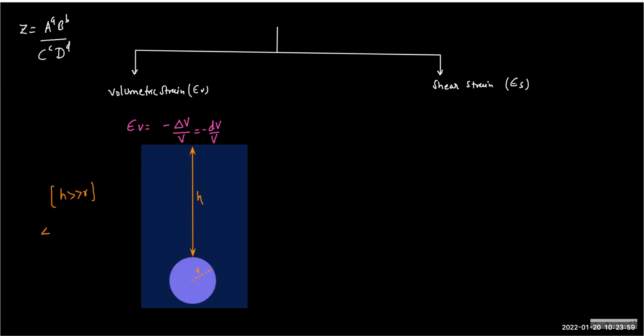So the extra pressure which we create is how much? Rho gh, correct? The additional pressure, the difference between the pressure at which it was manufactured and the pressure which it is experiencing right now, is rho gh, and that extra pressure needs to be balanced by the body. So to balance this extra pressure, it will get deformed slightly.